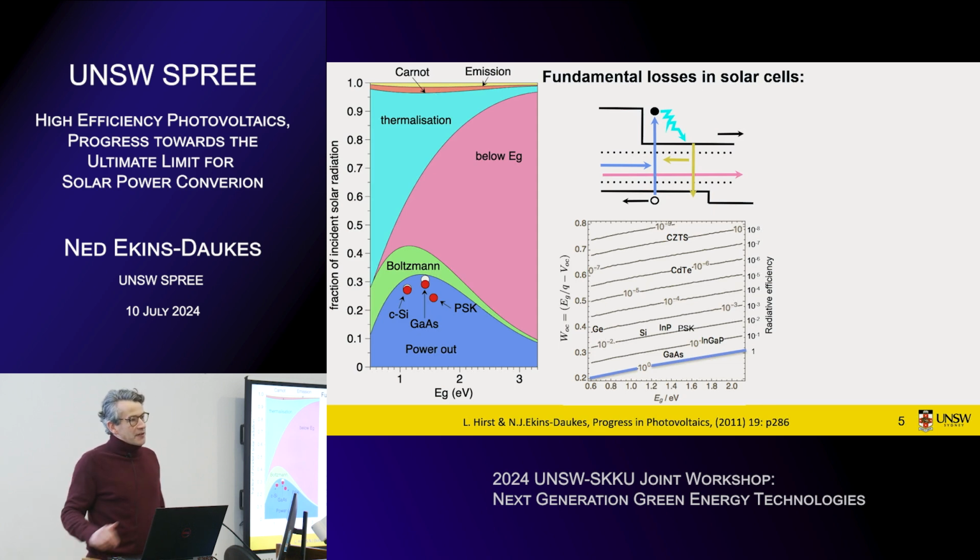If we were to walk outside this room and find some random person on the street and say, hey, I want to make the most efficient solar cell anyone's ever seen, do you think we should absorb all the sunlight in the solar spectrum? They'll say yes, of course. Why wouldn't you? But if we look at this chart, we can see why that won't work. If we take a very low bandgap semiconductor, then yes, indeed, we'll absorb all the photons, but this loss here that we call thermalization is going to be huge. So we get a very large current, we get a very tiny voltage, because the voltage of the solar cell can never be greater than the bandgap.